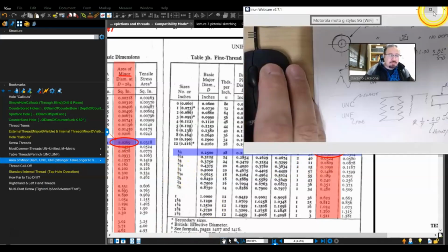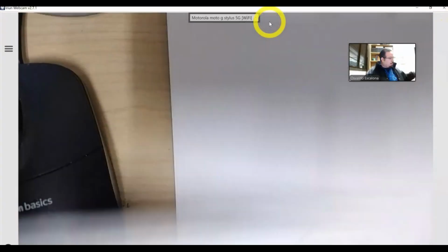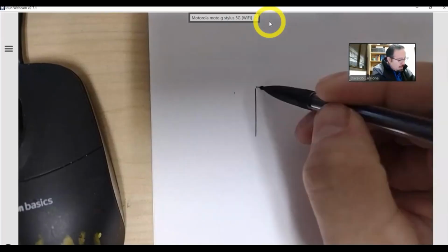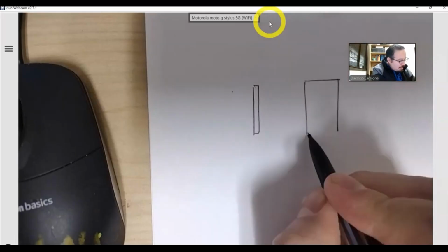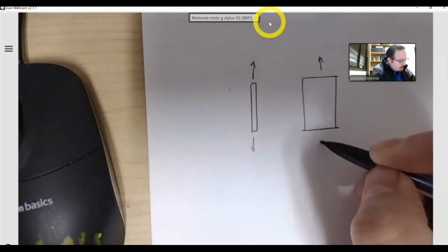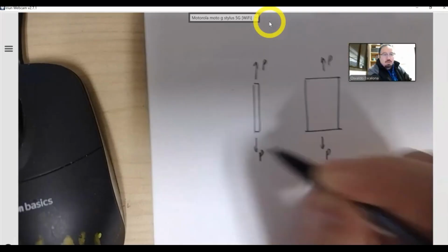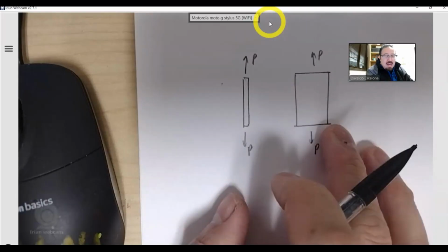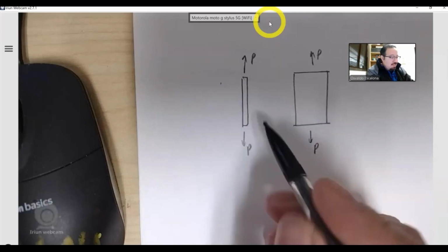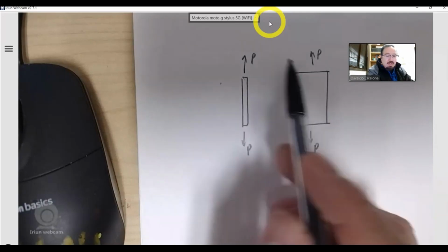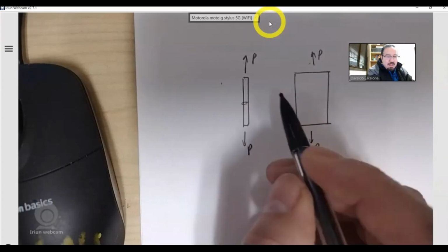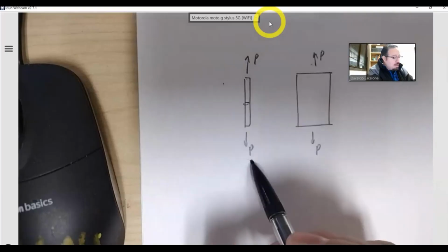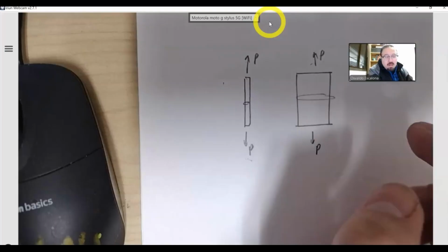What's the difference? Let's think about it, okay? I'm going to ask you which one will be stronger. I'm going to assume that these are cylindrical shapes, and I'm going to pull them apart with the same amount of force, a force that is increasing, and this is the same material. The load continues increasing until failure. The little area inside is going to go under tensile stresses. Internally, it has to carry the load that I'm putting, and the one that has the most area will be able to support more load.